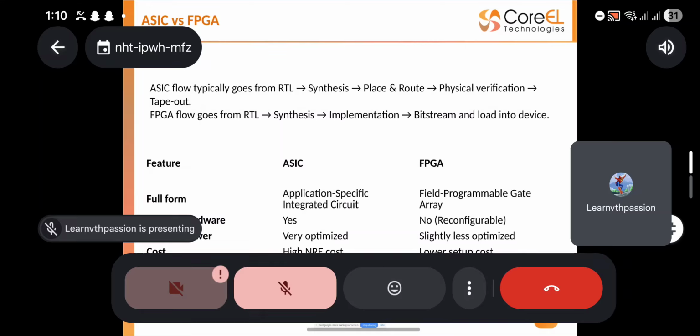You will have different boards, and each different FPGA board will have a different constraint file. We call it a Xilinx design constraint file. In that constraint file, for whatever board you have in hand, for example switches and LEDs, each will have different pins. The software should understand which pin I'm going to bitstream, because you are dumping your program into the hardware, and the software should understand where to dump my code. So you will do the constraints using the pin numbers.